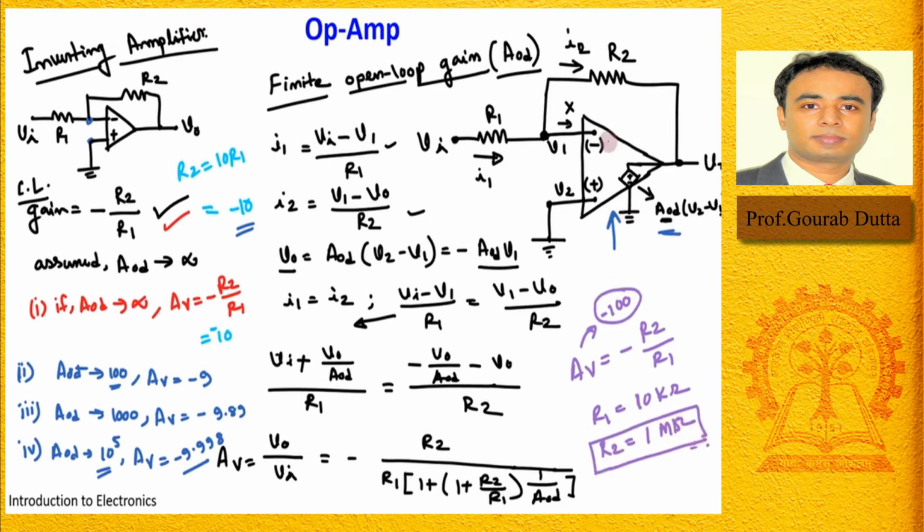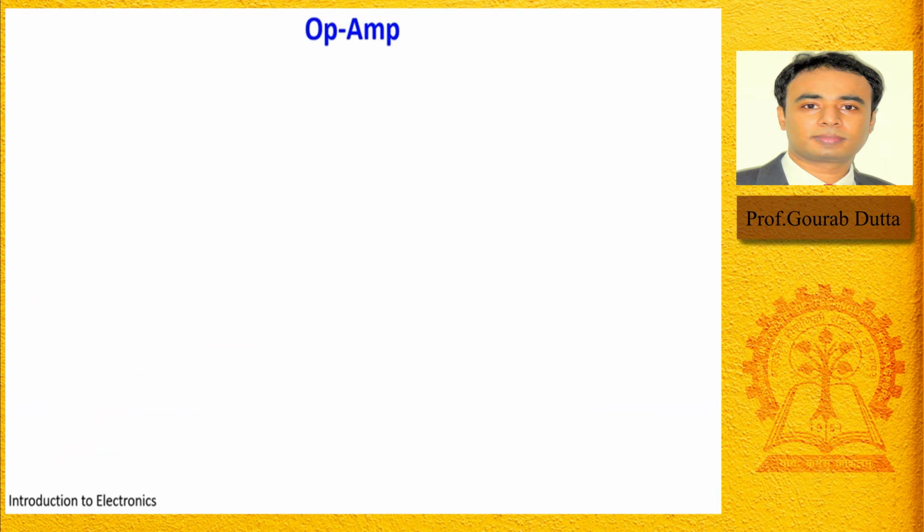Because then you have to use some resistor whose value is very high, right? And for any integrated circuit, implementing a very high value of resistance is quite difficult, right? So that is one aspect which we can solve in the next circuit. Let us see how. So here we are considering an inverting amplifier with T network.